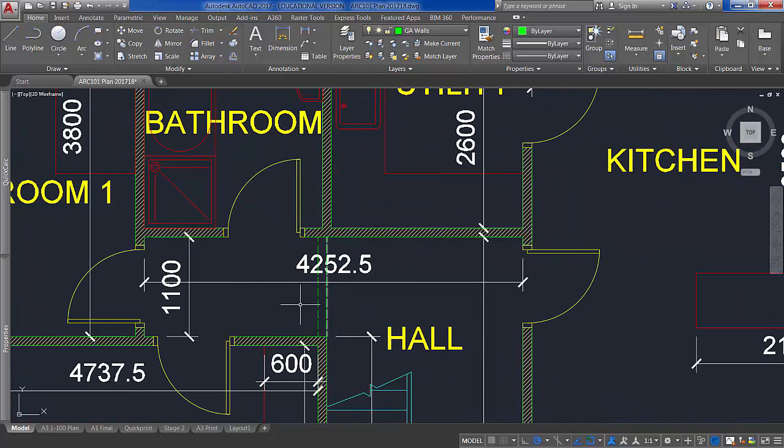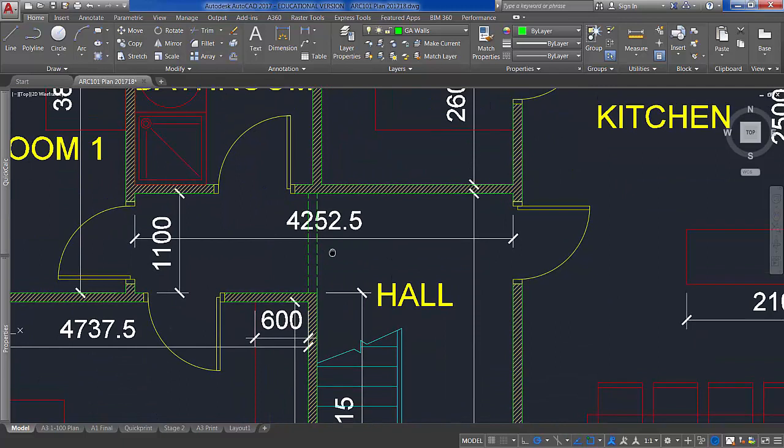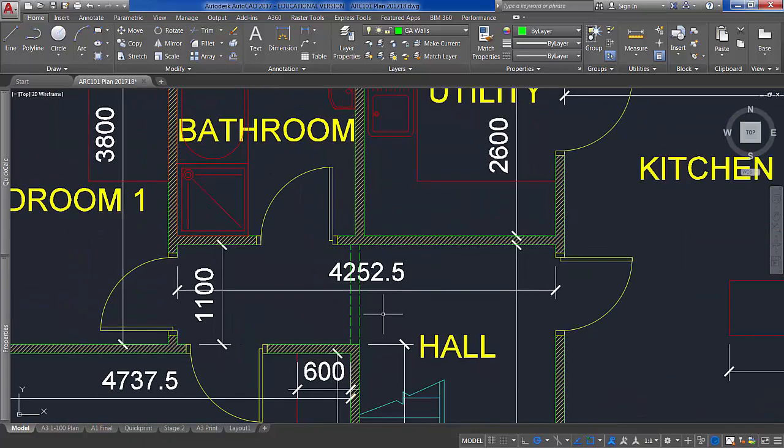And then you would also need to add an annotation onto your drawing just to indicate where that beam is and what it's carrying. And on either side, bearing in mind that you would need some sort of a pad foundation. That might not be just 100% accurate in terms of what you would be wanting to do, but that illustrates an example of where you might want to put a beam in.